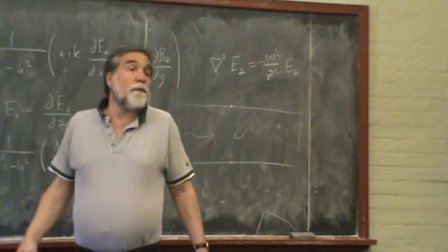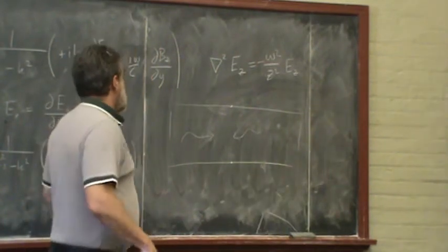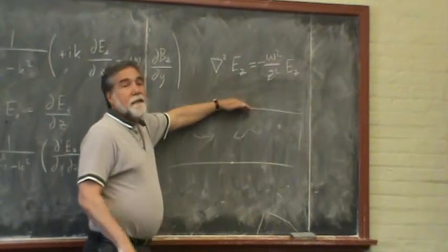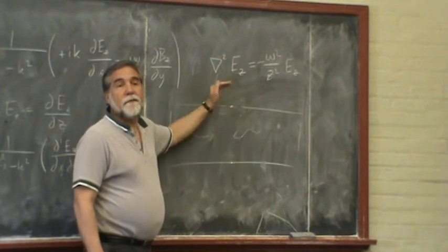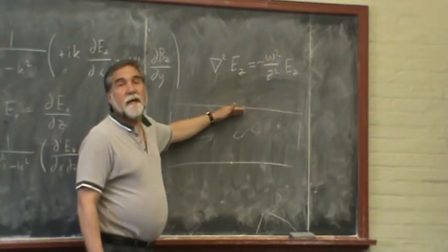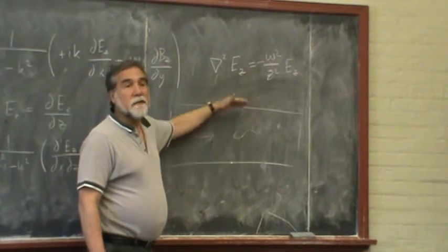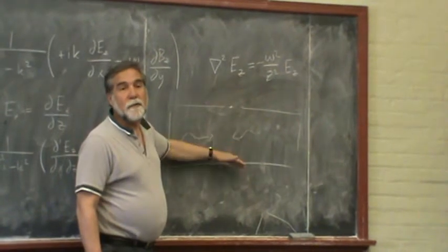And so if this were, for example, a rectangular waveguide or cavity, then the Ez field would have to be 0 here and there, and therefore, if this were x, I would have sine kx x solutions, where kx would have to have specific values that will be quantized.